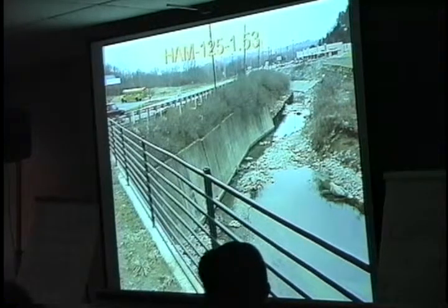The problem in this situation was this counterfort wall was being scoured, and the toe was being removed that way, and so then the shoulder along the road dropped, and the whole thing began to slide. Bedrock is in the creek or very shallow there. Down here, this slope was built a little steep. It's about a 1-to-1, and it also was showing signs of movement indicated by the leaning pole there.